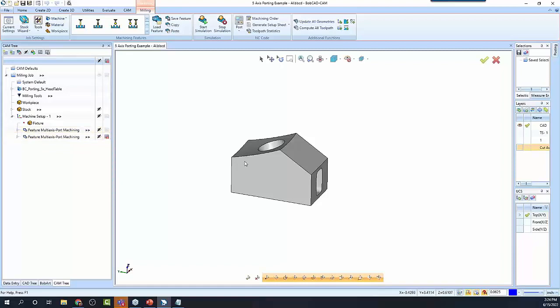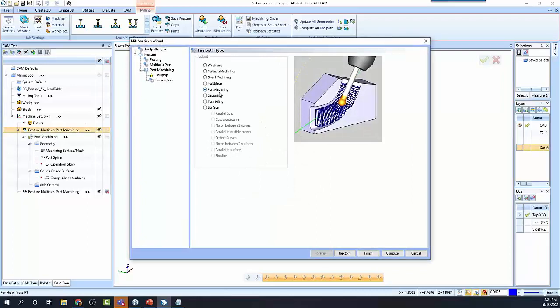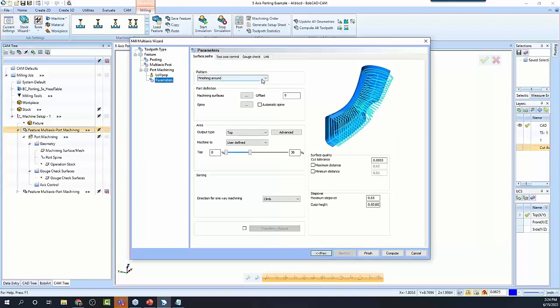All right. So to adjust the different modes, again, we're going to just edit this feature. This is going to be a port machining toolpath. When we're in our parameters, this section here is telling you what type of operation you're running, which is really like roughing, finishing along, finishing around, or rest roughing. Okay, so if you're going straight from billet, but you may have a cast part and you're bringing it in. A lot of different scenarios here, but a lot of the requests that I have to do with finishing and seeing the finishing on it.